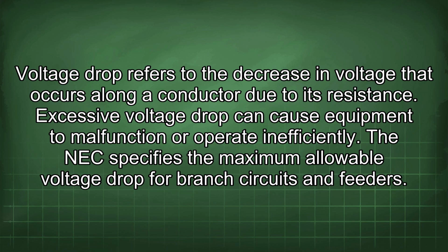Excessive voltage drop can cause equipment to malfunction or operate inefficiently. The NEC specifies the maximum allowable voltage drop for branch circuits and feeders.